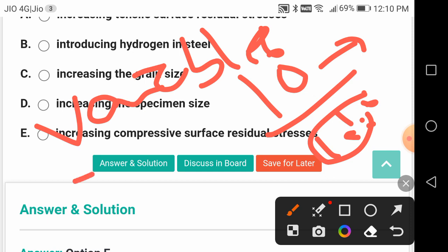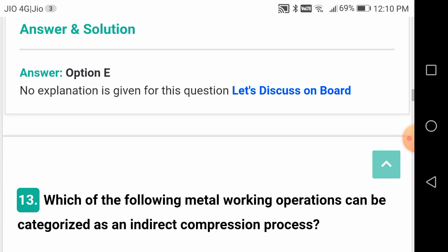Alternately compressive and tensile stresses, alternately sagging and hogging bending stresses, alternately clockwise shear stress and anti-clockwise shear stress. Any mechanical component is subjected to such type of stress. It is called variable loading.